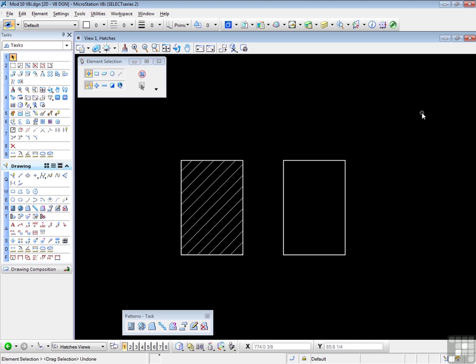It's very easy to set suitable values and place several plank layouts in copies of the deck outline. Similarly, if you're hatching a machine part and the material hatching symbol requires that the hatch spacing be 1/8 of an inch or 3 millimeters, you can control the spacing value so that the hatch will plot at 1/8 of an inch at whatever plot scale you're using.